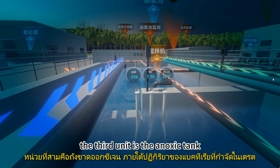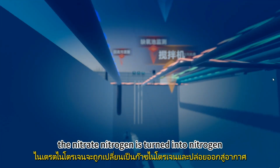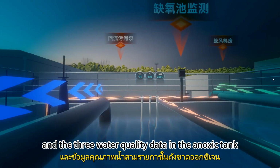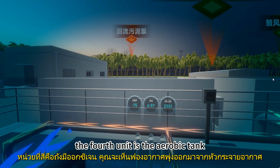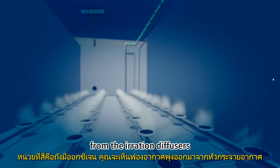The third unit is the anoxic tank. Under the reaction of denitrifying bacteria, the nitrate nitrogen is turned into nitrogen and released into the air, and the three water quality data in the anoxic tank can be monitored in real time. The fourth unit is the aerobic tank. You can see that the bubbles are gushing out from the aeration diffusers.